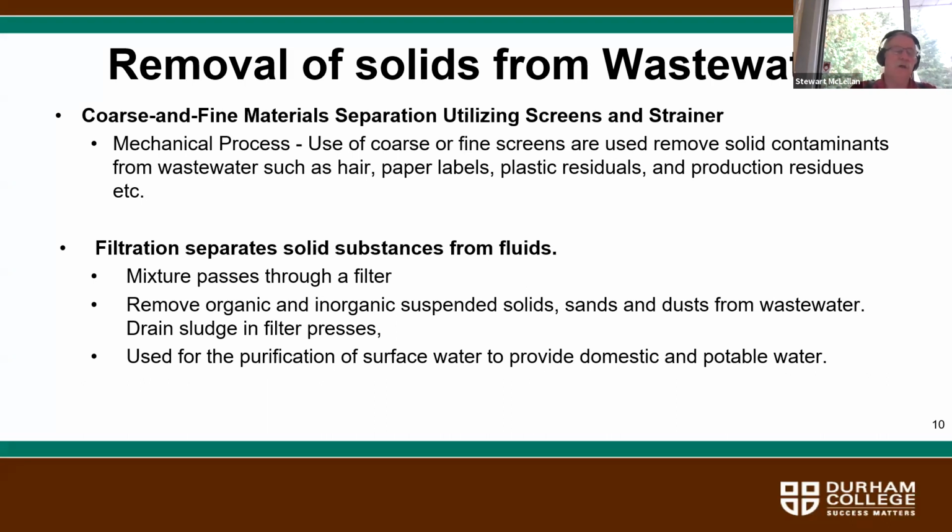Once the solids are removed from the water, they typically pass through a clarifier, and those solids are pumped from the bottom of the clarifier to a filter press, which compresses the solids into a cake-like material and reduces the water content of it, so that it can be more easily handled for shipment off-site as a waste product from industrial plants or from municipal wastewater treatment plants. It is usually used as an amendment on farmers' fields. Okay.